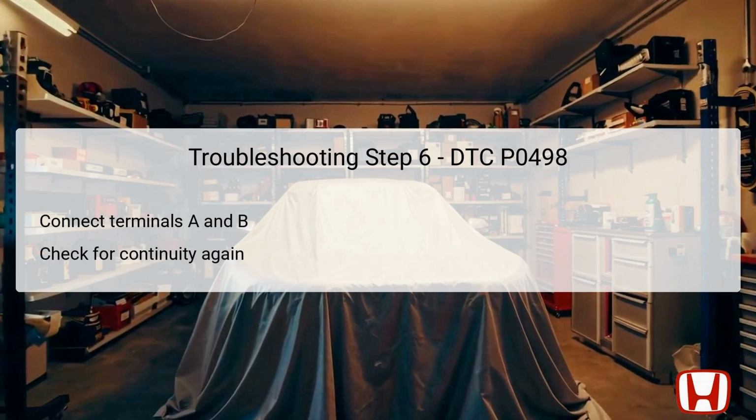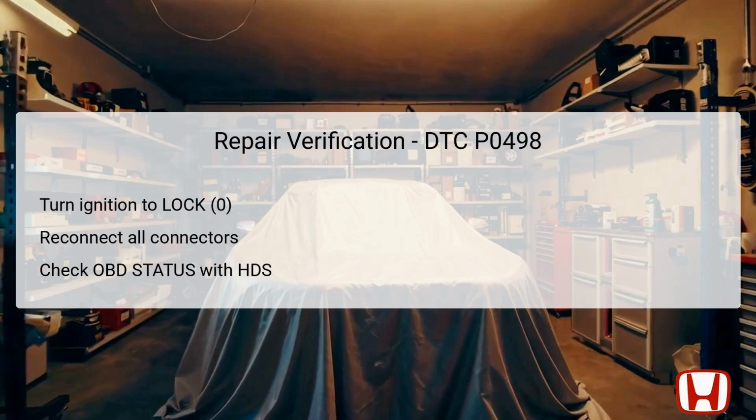If continuity does exist, it's crucial to ensure that the ECM has the latest software update, as outmoded software can sometimes lead to errors in functionality. If continuity does not check out, it indicates an open circuit within the VSV wiring that must be repaired before concluding the diagnosis. After completing all the necessary repairs, it is essential to perform a thorough repair verification to confirm that the DTC P0498 issue has been resolved.